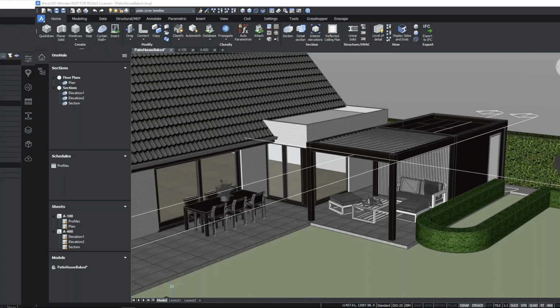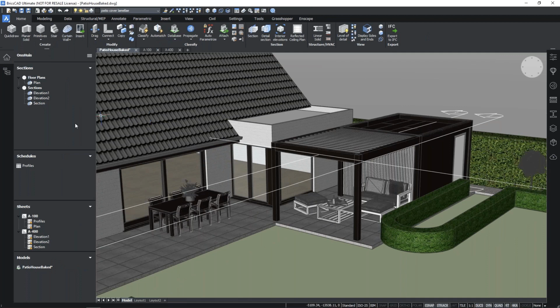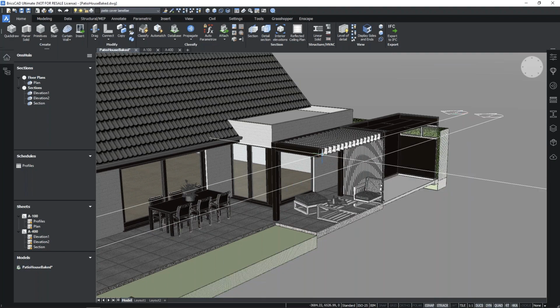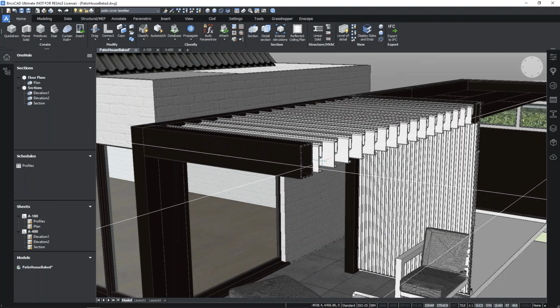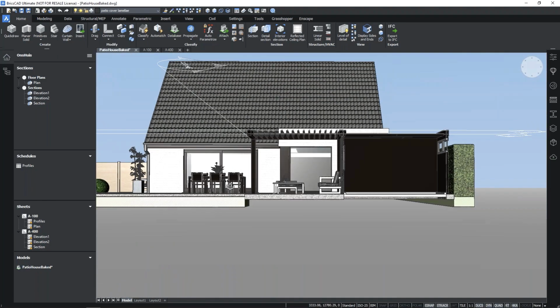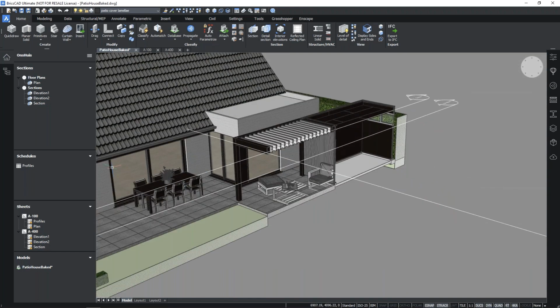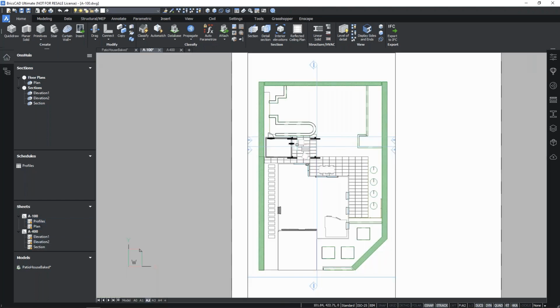So, once you have your project, you can see that this is, for example, a finished project where I made sections and plans. If I just open that one up, it's just as before, but now instead of being preview geometry, it's real baked geometry. So you can see how the section looks, but you would want this section to also come onto a sheet. So that's very easy in BricsCAD. You just have your project browser, you select everything, you set your sheets in sheet setup, and then I can display the view, which is here.